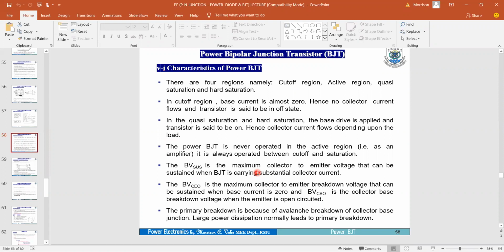So when we are using that switching behavior to control a process, these power electronic devices that we are talking about, we are more interested in them as a switch. And for a transistor, we are not going to use it as an amplifier, but as a switch, okay? All right. So our device here will be operated between cutoff and then saturation, okay?